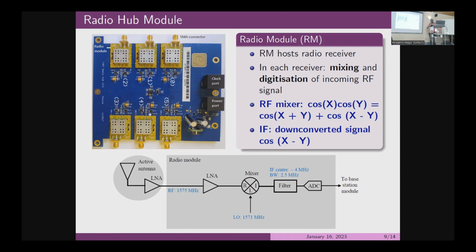So what it does is this. I said this is an active antenna. So you amplify your analog signal, then it comes in. Now, in the older days, once you have the signal here, you put a filter, because you only need a particular frequency, right? So you put a filter here with a narrow band. But the problem with that is, if you need another signal, you have to tune your filter. Now that already affects the stability of the filter, right? Two, manufacturing narrowband filters was also a problem.